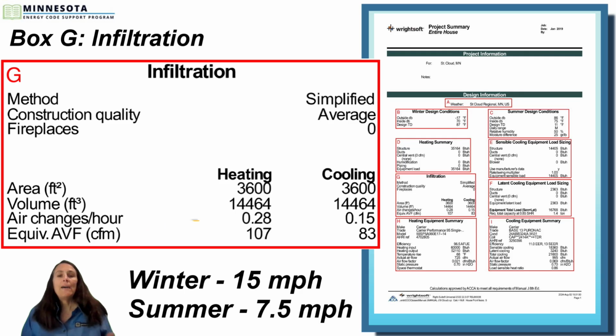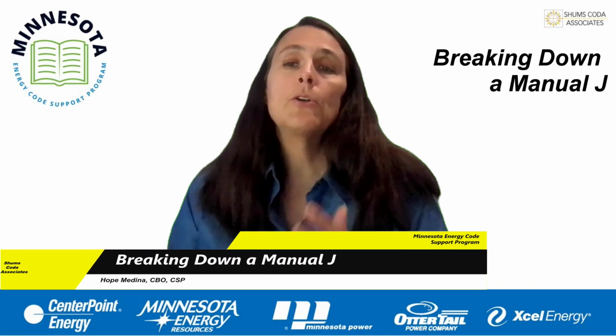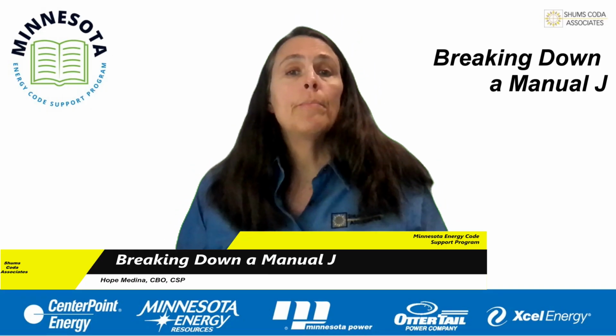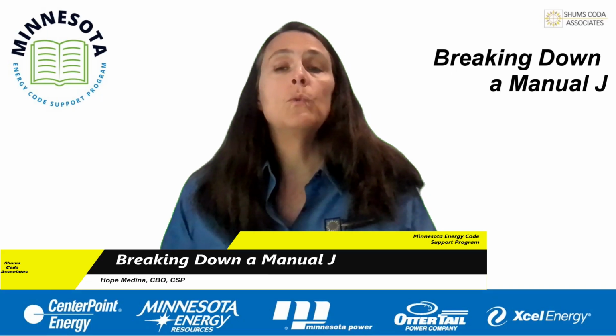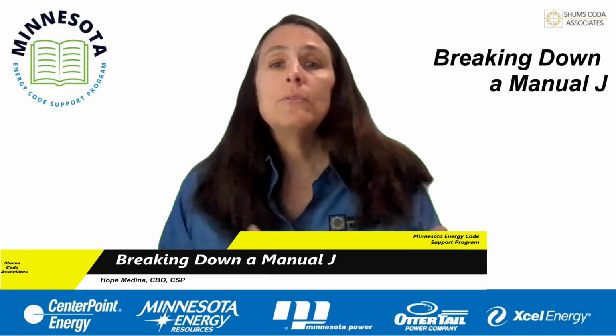Now, these are the values from the average construction type that's been listed above. And the reason this is different is that the heating is done with a 15-mile-per-hour wind and the cooling is done with a 7.5-mile-per-hour wind. The last row is the equivalent AVF or CFM, and this is the number of CFM that's coming through the walls. How leaky is it? These are the boxes of this report that are attributed to a manual J. Now, if you notice, we did not talk about box H or box I, and that's because these are associated with a manual S. So join us for our next video as we break down a manual S.